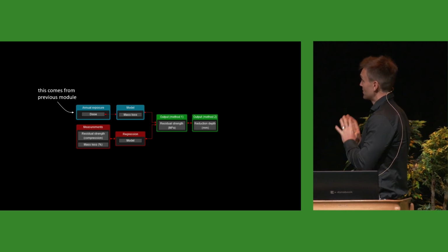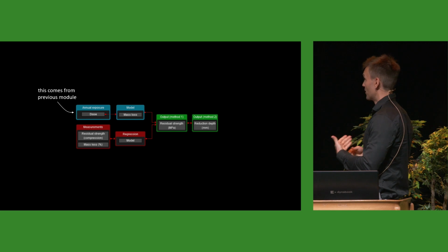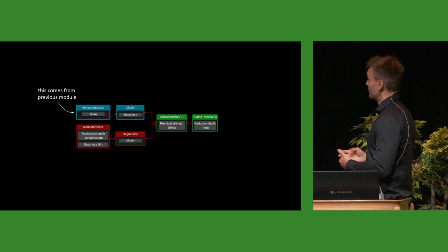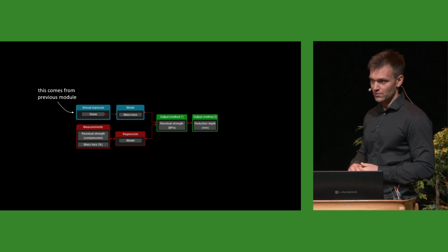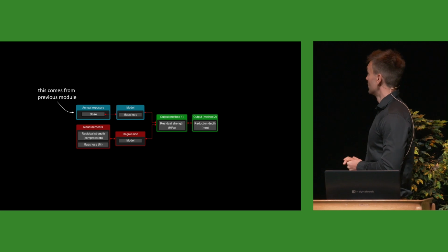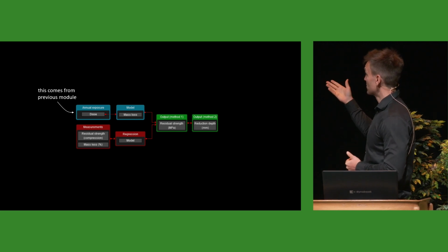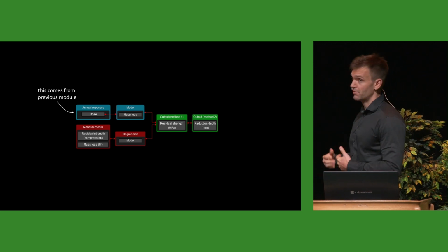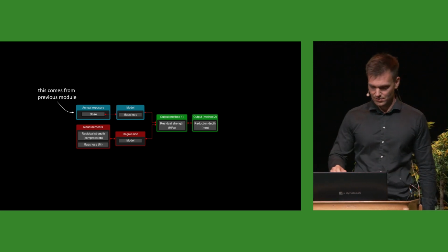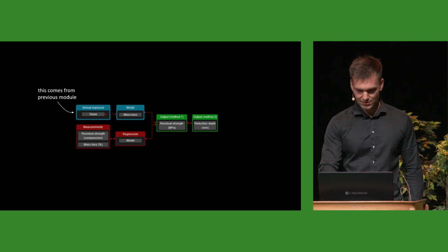So based on mass loss, we can calculate the residual strength of a component. You will see that we have two different ways to present this, either as residual strength for a given mass loss or a reduced cross-section, similar to how you would deal with damage caused by fire, as we learned yesterday.